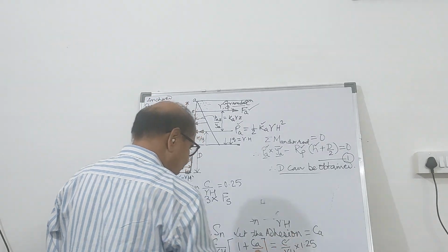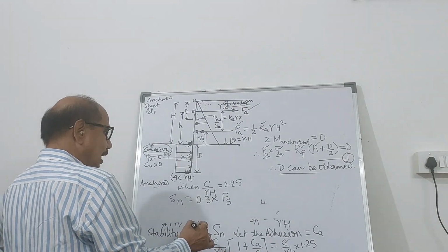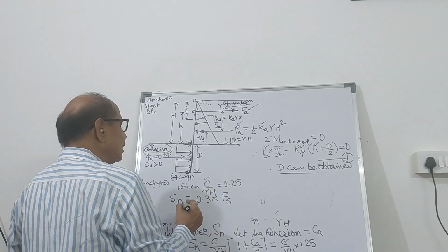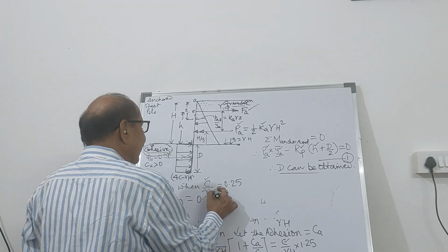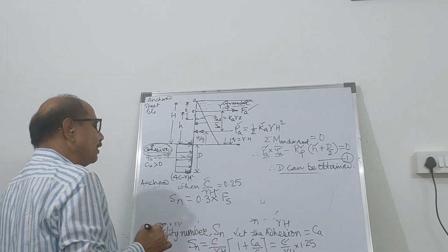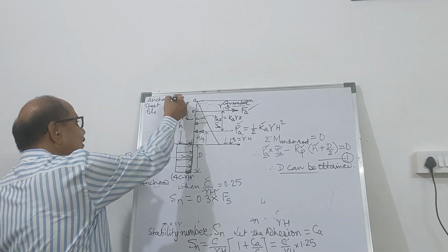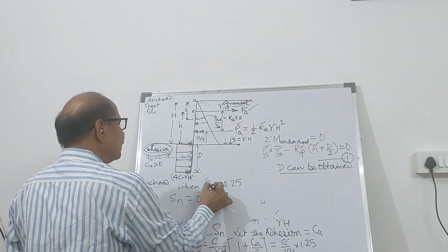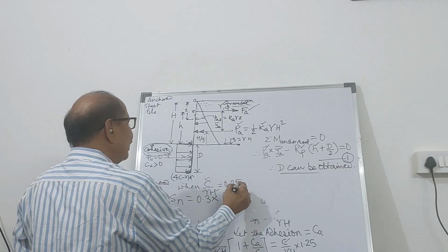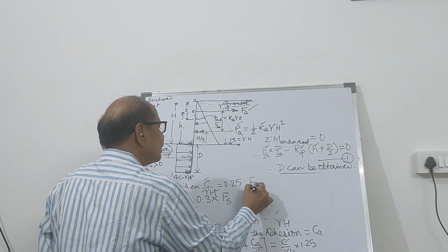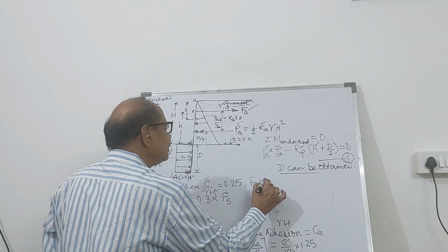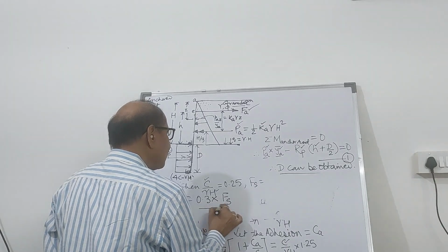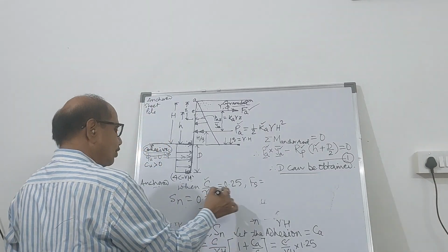C is the ground property, which is going to be constant for the given ground. Gamma is going to be constant, and this h value is the height of the sheet pile. So when Fs is critical, it's unstable, so you must multiply it by the factor of safety.